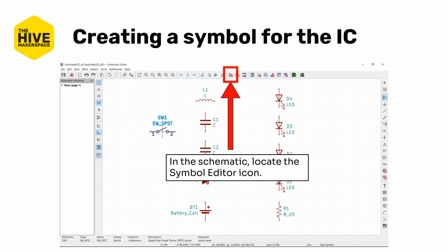So back in the schematic view, to make a symbol, we need to go into the symbol editor, which can be accessed directly from the project window, that main project window that opens, or directly from the schematic using this icon here, kind of in the middle. It also looks like a little op amp with a little red circle and a check mark at its nose.